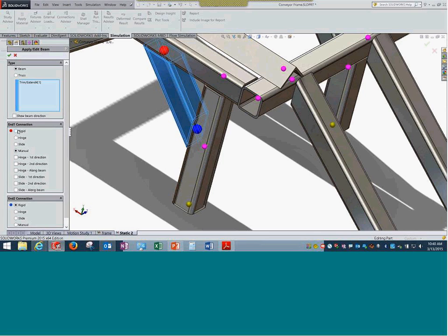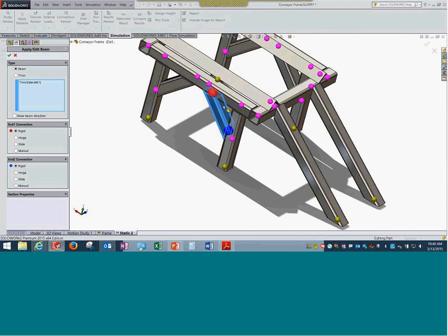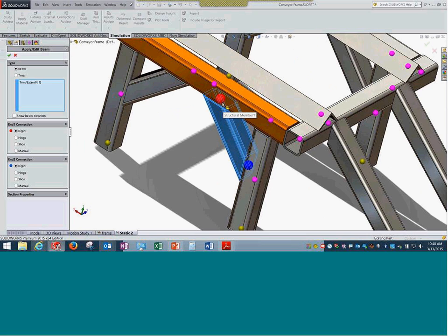That is, all 6 degrees of freedom from each joint are transferred to the other joint. If you remember, we have already discussed that a beam node has 6 degrees of freedom. Use this option, and we are telling that all these 6 are getting transferred. If you don't want that, there could be cases like huge bridge structures which are connected with pins. Those would be cases wherein it is a kind of hinged condition.